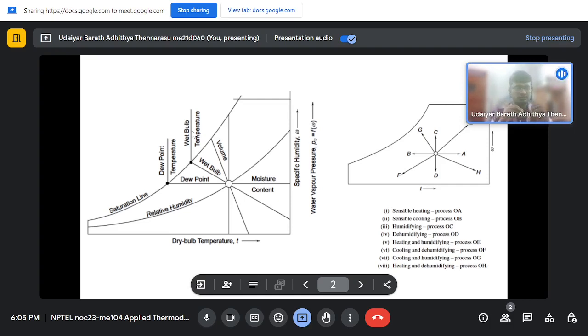You put it in the thermometer bulb, and what will happen is air will pick up this water. It will take away some water vapor, and while evaporating, the water will take away some heat from the water in the cloth, and the temperature of the cloth will go down. Correspondingly, it will reach a steady state where the temperature is at a saturated condition. In that case your temperature is called the wet bulb temperature,